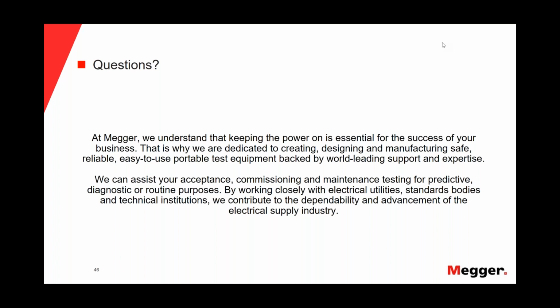For instance, if somebody bent the cable too much and crushed the jacket and inflicted mechanical damage to the insulation, then we will detect that problem, but because we have a mechanical damage in the insulation. But after the question, I will say no. With partial discharge, we cannot detect issues in the shield or the jacket of the cable. We need to do the sheath test to find that kind of issues.